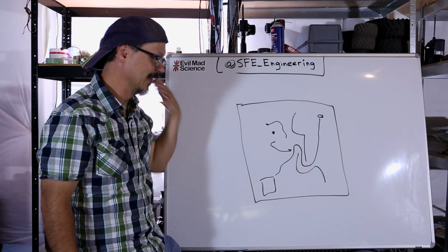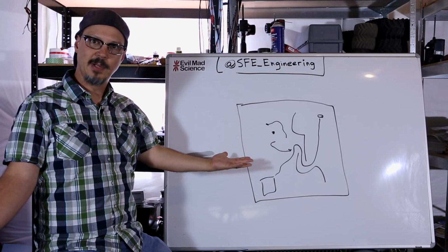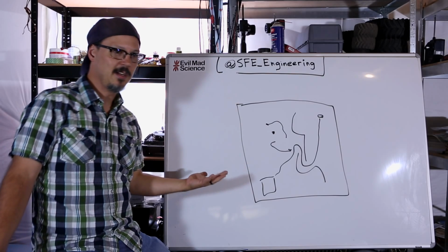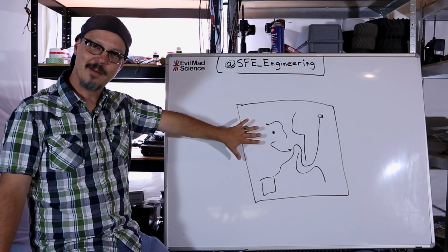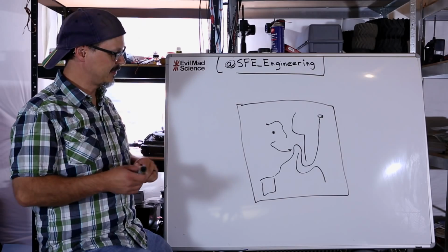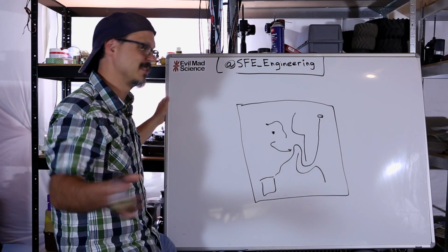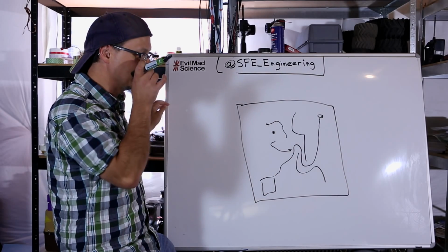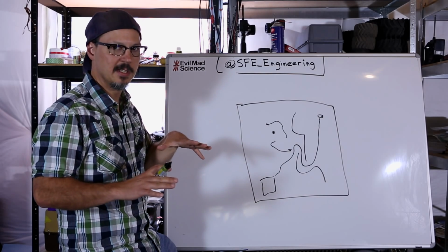I want it to be a little beefier, and I want it to be straighter. Some of you might be going, what? No VCC plane? Well, no, right? Remember, two-layer board, but you can have VCC on the top of your board just fine. Well, you can, but you're going to have a lot of traces on the top. When I lay out a circuit board, I have a lot of traces on the top, and it's harder to maintain a full plane of VCC that way.